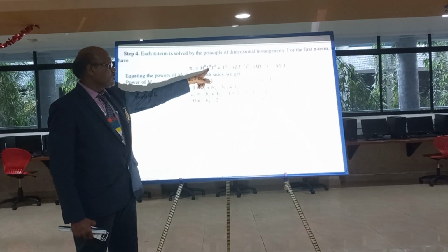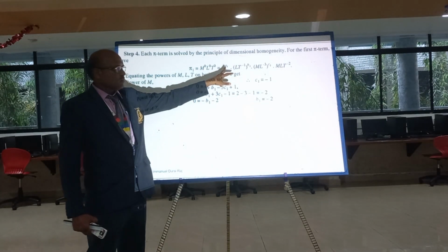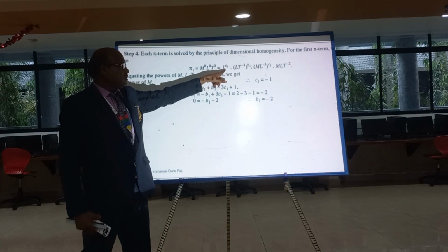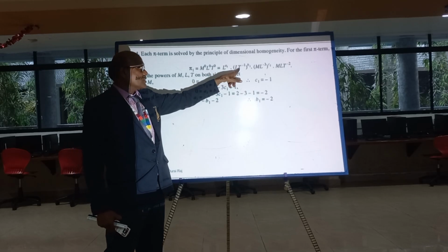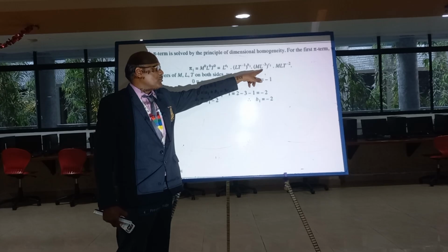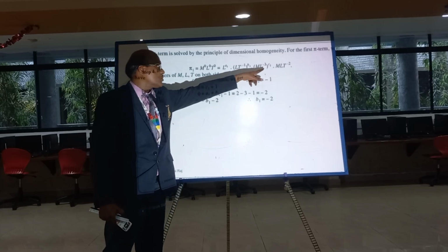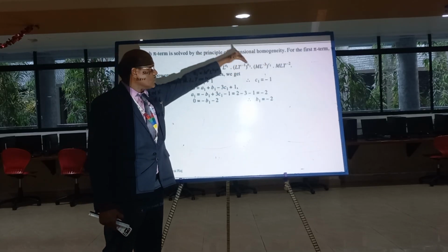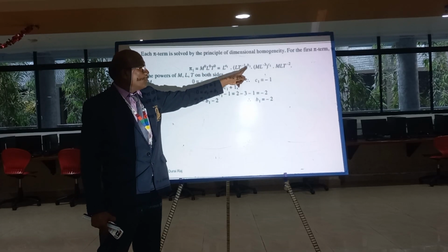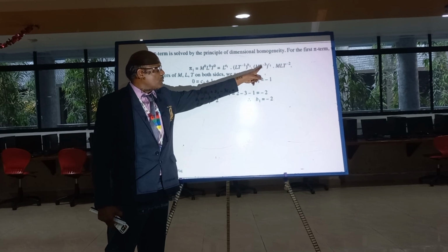I can write M0 L0 T0. Always you write phi 1, phi 2, phi 3, these terms, and you write the repeating variables here: L, V, rho, R. For L, length, put L. For V, meter per second, L T power minus 1, and density, kg per meter cube, M L power minus 3. Resistance is M L T power minus 2. Put A1, B1, C1 on the top. So multiplying inside: L power A1, L power B1, T power minus B1, M power C1, L power minus 3C1.